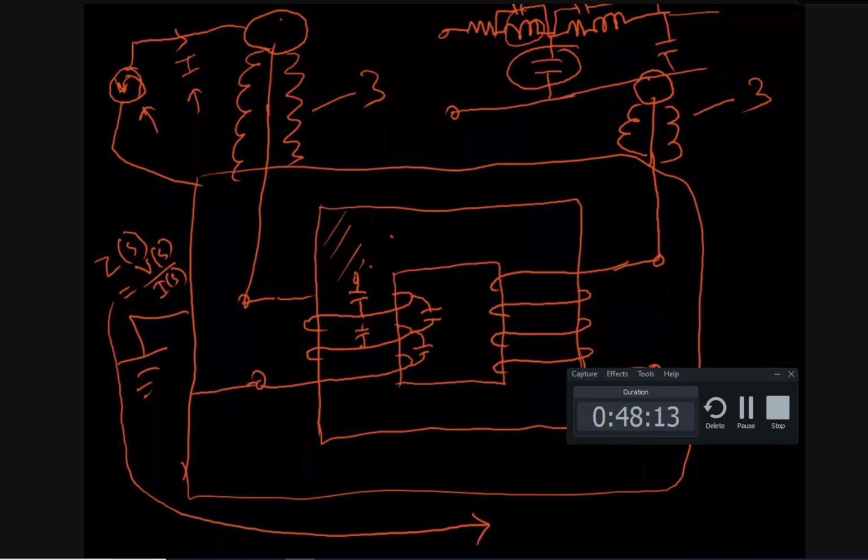Over a period of time, at regular intervals, I'll go and check the same characteristics from the terminals, V of S by I of S, and find the frequency characteristics, which is known as swept frequency response analysis, SFRA. Of course, I'm not talking about that now. Using that you can synthesize a network. So each time I will compare my synthesized network with the original network and see if there are any parameter changes.